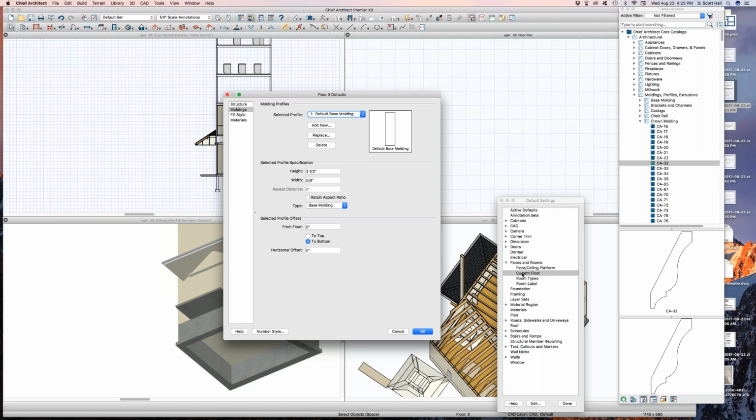Oh, is it in a room though? Did you put it in a room or? Yeah, I went in and named the foundation. I just named it slab, I think it was, and then I said I wanted it to extrude on the outside. Yeah. And then I had to offset it down 6 inches or something, and over like 20 inches to get through the foundation, to get it off the footings.